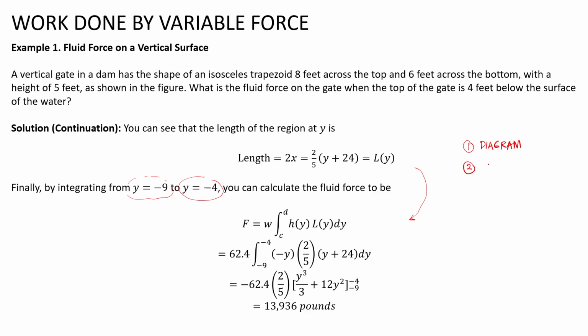So next step is x and y axis. Establish x and y axis. So x-axis at the surface of the water, surface of liquid. Y-axis is at the center of polygon.